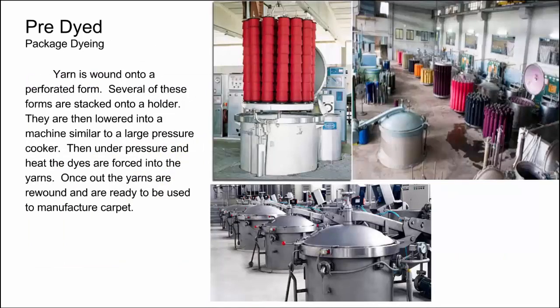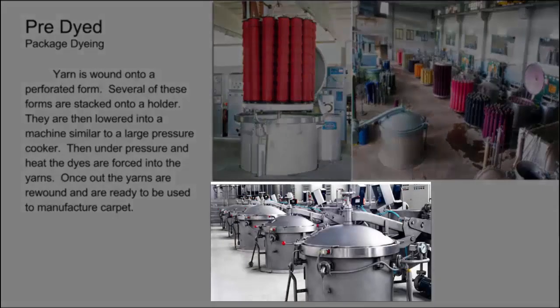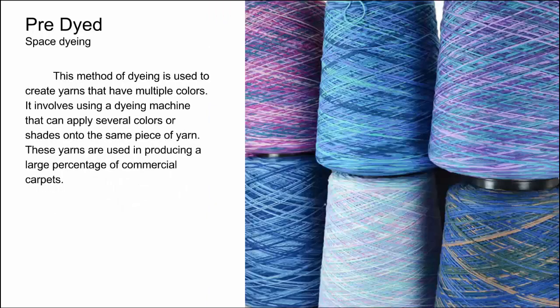So first of the pre-dyeing methods, we have package dyeing. The yarn is going to be wound onto a perforated form or a cone. And then you're going to have a whole stack of these that are loaded onto a holder. You can see there in the picture on the top left, those are already dyed yarns stacked onto the holder. They're lowered into these vats or machines, and they're under pressure and under heat. The dyes are forced into dye sites of the carpet. Once the yarns are done and they're dyed, they're rewound back onto their original cones, and they're ready to use to manufacture carpet.